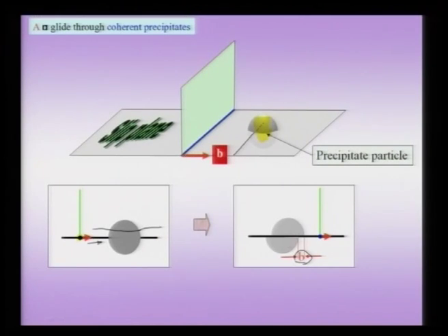But in any case, the section lying within the precipitate would face a higher Peierls stress to move the dislocation, and therefore you will see a hardening effect even though the dislocation is actually gliding through the precipitate.